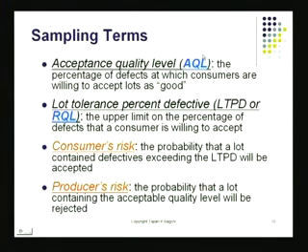For example, there is something called AQL, which is the acceptable quality level. Acceptable quality level is that level of quality that I am willing to live with, as a user. It's generally expressed in percent level. Generally speaking, if the quality level of a lot is at AQL level, it is all right for me to bring this into my shop and start using those parts on an average basis. But then it's very possible that the lot that I receive is at this level, which is the RQL level, rejection quality level.